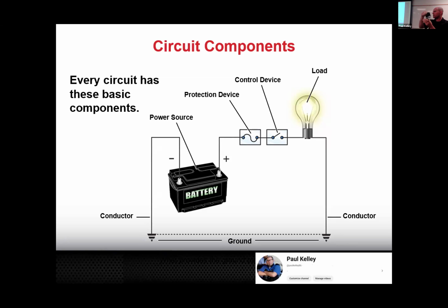All the voltage should drop here. We shouldn't have voltage dropping here and not giving this enough voltage, because then this is going to glow dimly. Wait a minute, this doesn't glow. What do you think it would do? Yeah, it wouldn't sound right. You'd be like, oh, my horn sounds sad and weak. You'd be like, oh, it's probably got a voltage drop, an unwanted resistance in the circuit. And so you're diagnosing very much the same as a bulb, except it could be the horn or something.